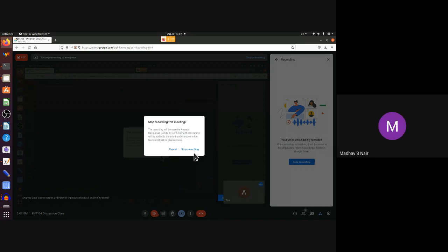Okay. Yes, sir. I was getting a little confused about why the AC analysis is done separately. It's just like when you do superposition with multiple sources, you take one source, find out its result. You take the other source, find out its result. But when you're taking one source, you replace the other source by its internal impedance. Here, the DC sources, you take them to get the biasing. For the AC part, you just consider the AC signal. And the DC parts, you replace by the internal impedance. And the actual answer is the sum of the two.